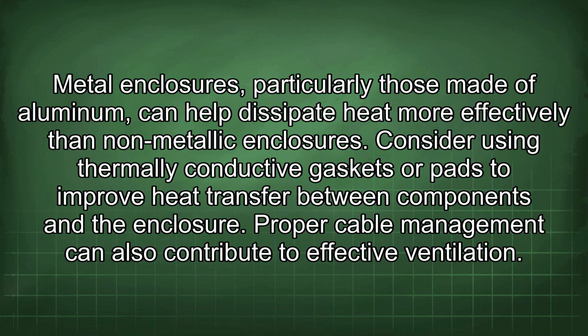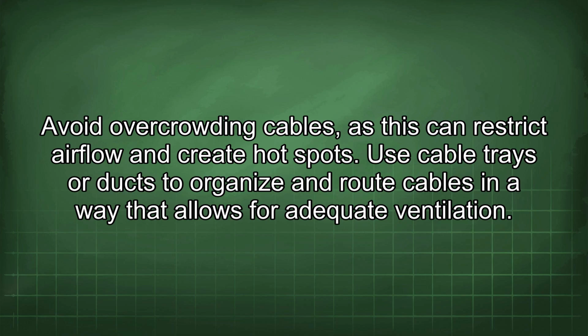Proper cable management can also contribute to effective ventilation. Avoid overcrowding cables, as this can restrict airflow and create hotspots. Use cable trays or ducts to organize and route cables in a way that allows for adequate ventilation.